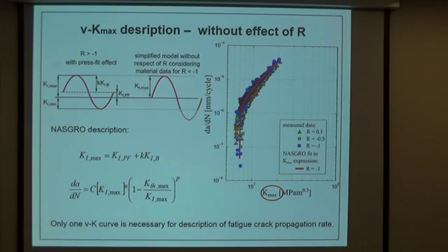And you can see that if we use the material data which were measured on the lowest operation stress ratio, in our case -1, then we will obtain conservative results, because as you see in the linear area, the data measured for stress ratio -1 creates an envelope of the other 2 measured decay curves.